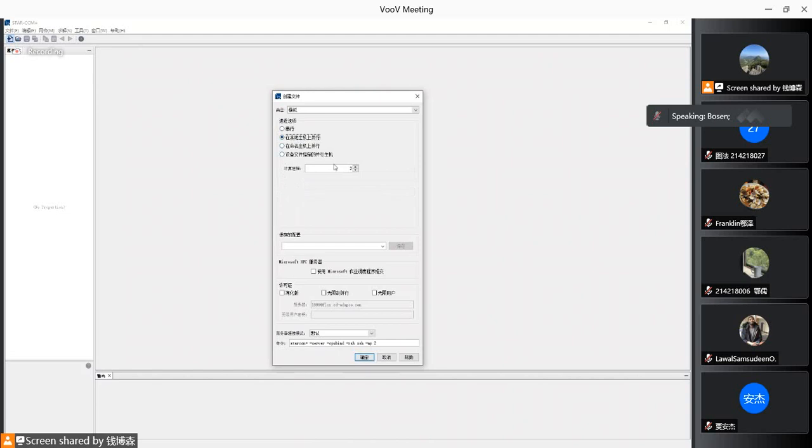Rather, I suggest you use the parallel computing process. It will be very convenient in both the domain discretization as well as the computational process. Okay, but remember, this number should not exceed your maximum number of cores. For example, your computer only has 8 cores, and you put a 12 in here.